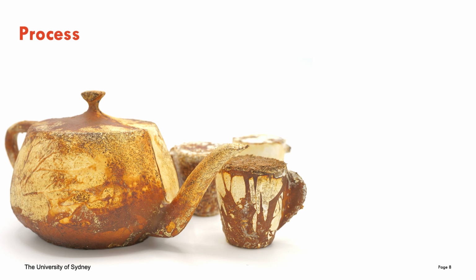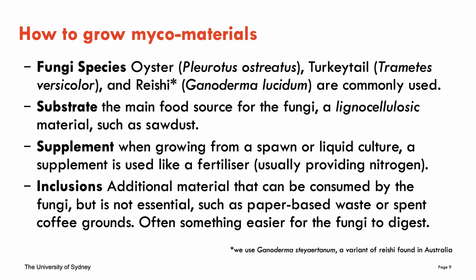So let's start with the process. The four things that come together to grow myco-materials are the fungi species. In literature, we often see oyster, turkeytail, and reishi being used. It requires a substrate for the fungus to grow on, often a wood-based material or a waste such as sawdust or paper-based waste. It requires a supplement similar to a fertilizer and usually provides nitrogen, and as our examples will show, we can also have inclusions. These are additional materials that can be consumed by the fungi but are not the essential food that it needs. Examples are paper-based waste or spent coffee grounds.